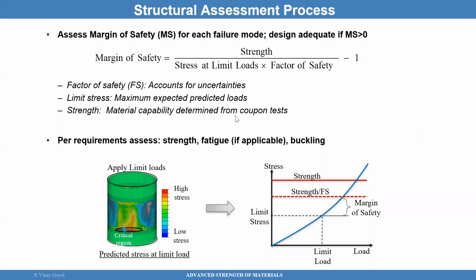So some industries will use a higher factor than 1.5, and I'm just giving you some key numbers. If you test, those are good numbers. If you don't test, some industries will use a factor of 2.0. Say it's a pressure vessel with a lot of safety concerns. You may have to use a 4.0 or 3.0, depending upon the industry that's regulating you, right? But the factor of safety can be very high depending upon the application.